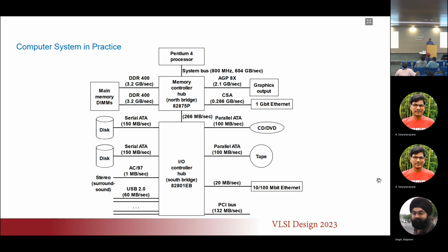Then my tile is in the memory, in the cache or local memory, but I cannot put so many adders and multipliers to process the entire tile all at once because it'll be too many adders and too many multipliers. So I can only, in the hardware, do a portion of the tile. When I do a portion of the tile, that portion must be an integral subdivision of the whole tile. Because if it is not, then there'll be wasted time when I'm fetching only a part of the thing and I'm doing operations and they're going unused. Is that clear?